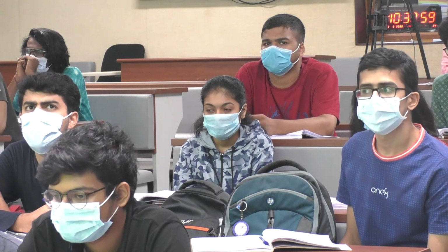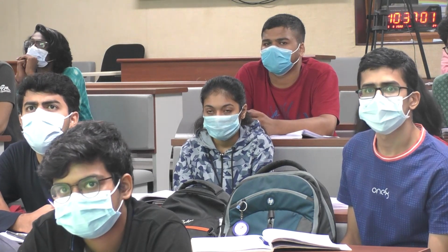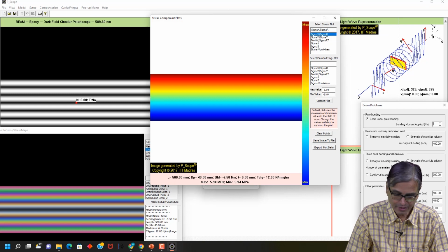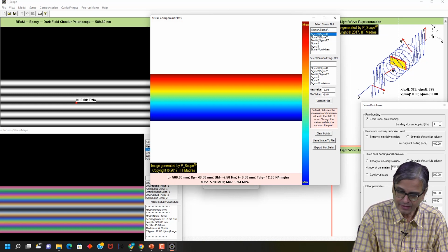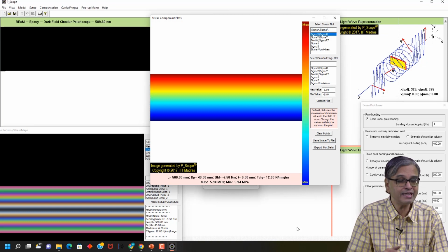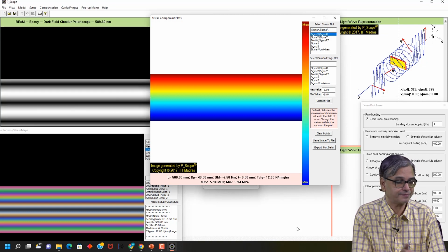Think about it, okay. Now, I will take one more example to show the principal stress direction, but here I am going to make the load minus 4, something close to half, and I would see fewer fringes, okay.